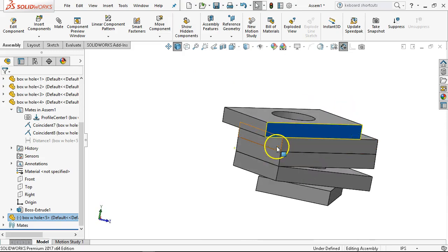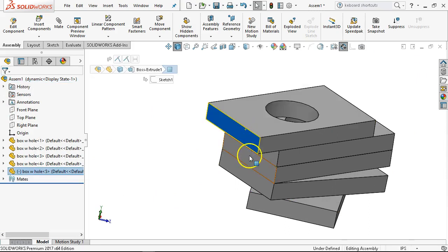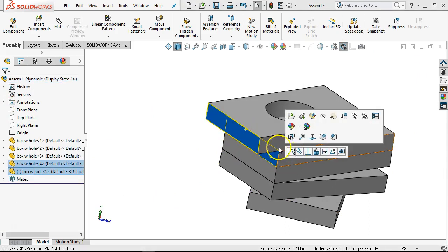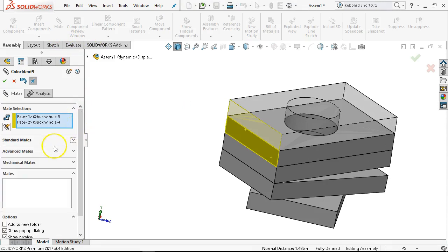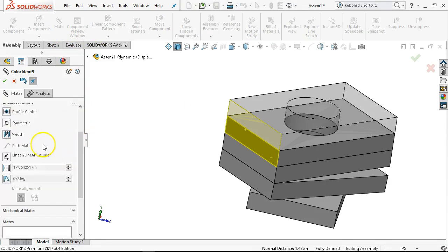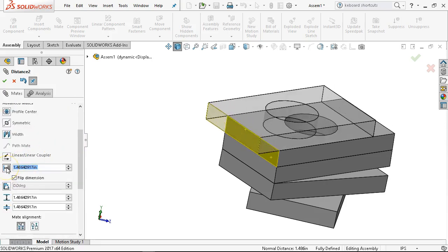All right, so get it into a position that we can manage it. And then face to face is going to be a limit distance. Its current position is 1.5. Maximum will be 7 inches. Minimum will be 0. So I have just a little bit of overlap.